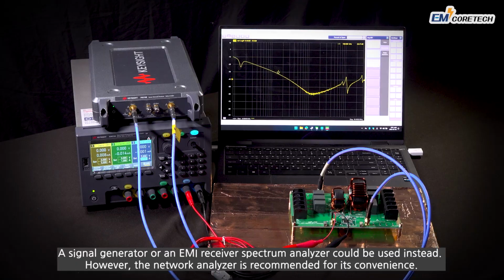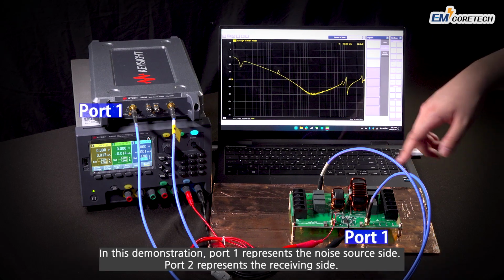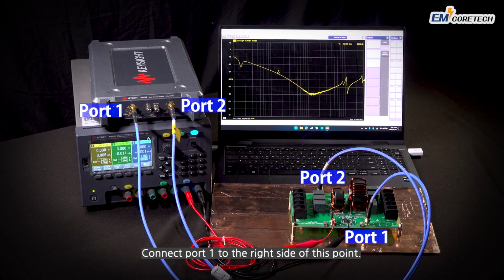A signal generator or an EMI receiver spectrum analyzer could be used instead. However, the network analyzer is recommended for its convenience. In this demonstration, port 1 represents the noise source side. Port 2 represents the receiving side. Connect port 1 to the right side of this point.